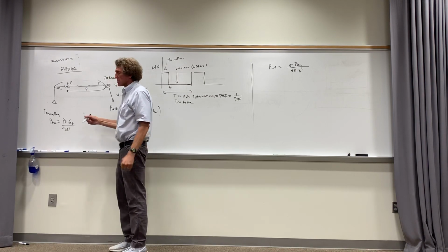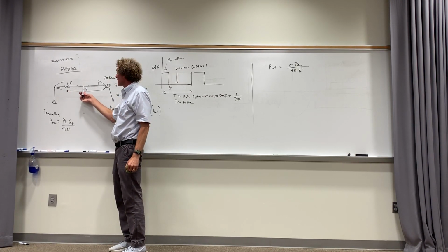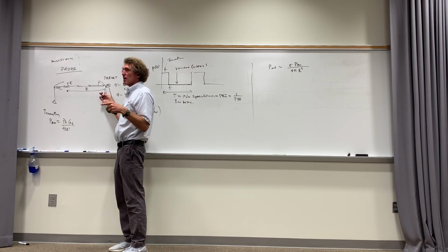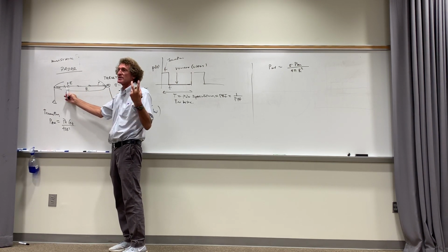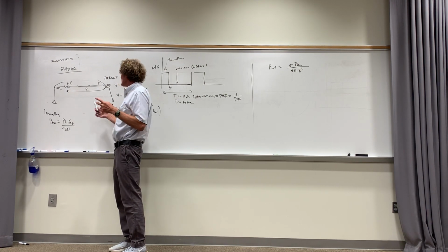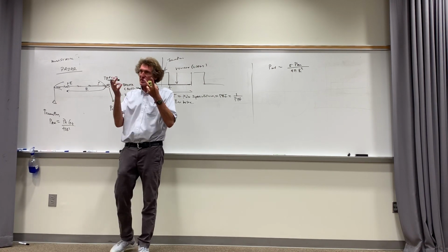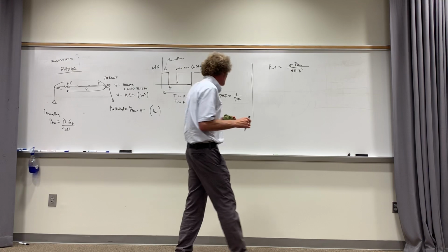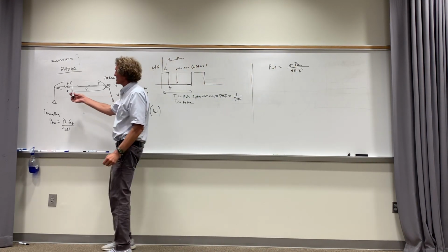Follow me? So the way it works, I have a power transmitted, P transmitted times gain over 4 pi r squared that hits this, multiplied by sigma, that's the total power reflected. And how much is reflected back here? That total power divided by 4 pi r squared, because there isn't that gain effect. Do you understand, class? And any focusing ability of this would be included in sigma. All right, it would increase its value if there was any focusing. So that's the amount of power reflected that's coming back and striking this antenna.